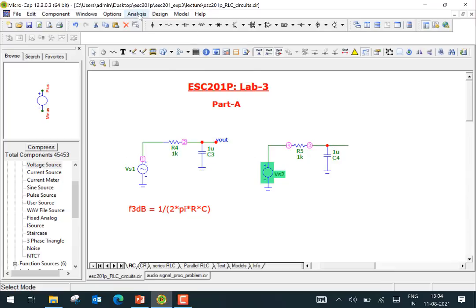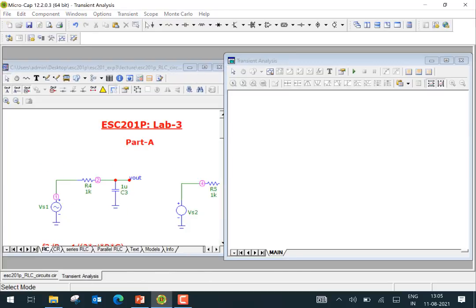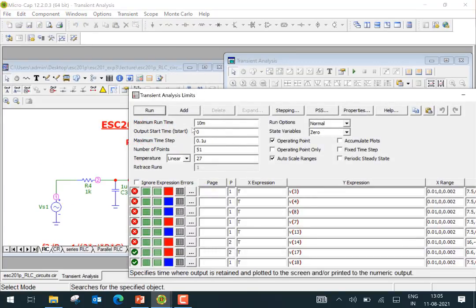And let's do transient analysis. Keep in mind, V3 is the output and V4 is the input here. We are doing the transient analysis over one period, 10 milliseconds. A maximum time step of 0.1 microsecond is not necessary. We can make it 1 microsecond, which should work fine. We should have enough resolution in the time domain to capture the waveform properly.